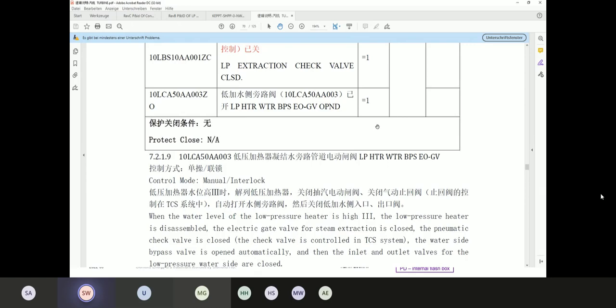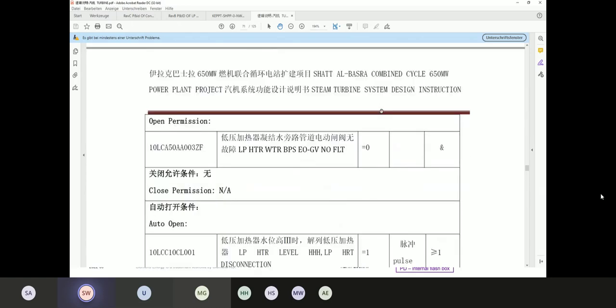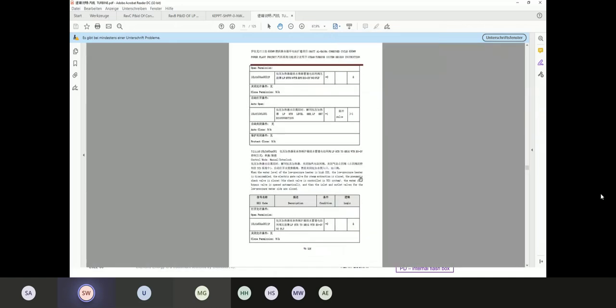And I mean, with this system it must be somewhere in, because when it's not in and the level is low, you will get in trouble with the pumps, because the pumps will not have the required NPSH. When the NPSH is not there, you get cavitation on the suction side, and you will hear it. The pumps will get noisy, and they will more or less destroy your impeller. And that's what we from Siemens for sure want to avoid.